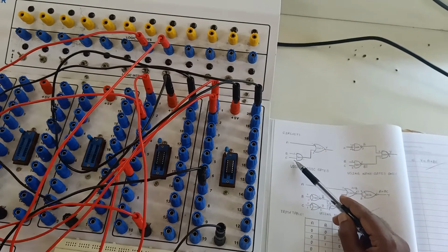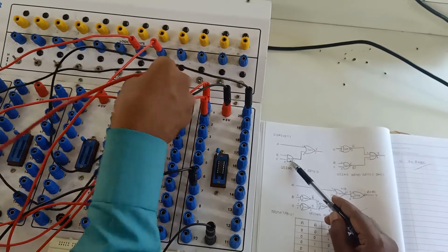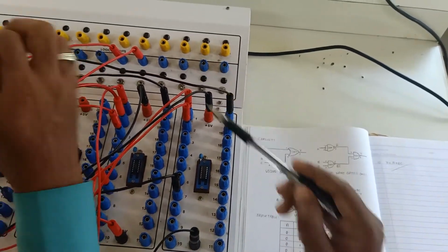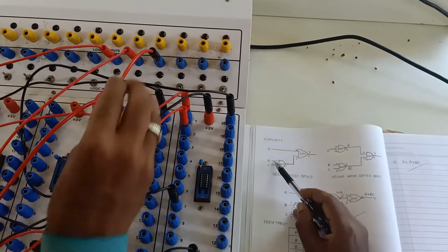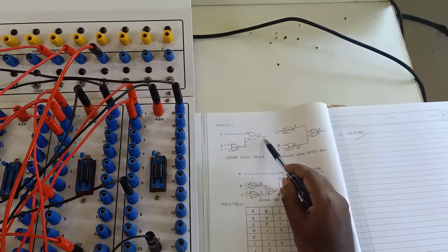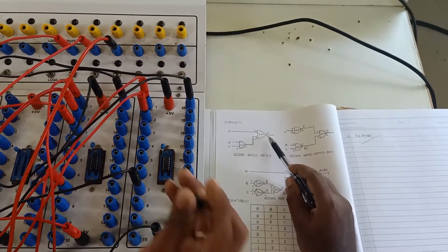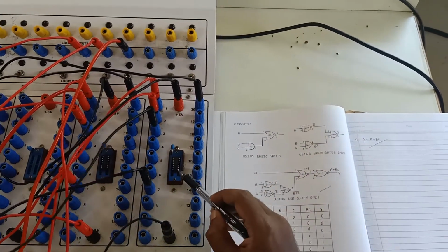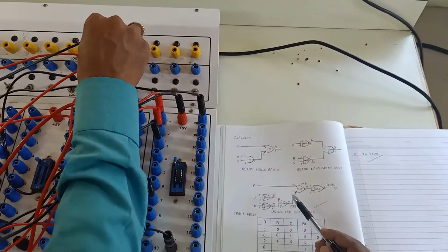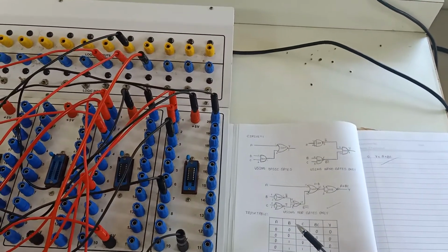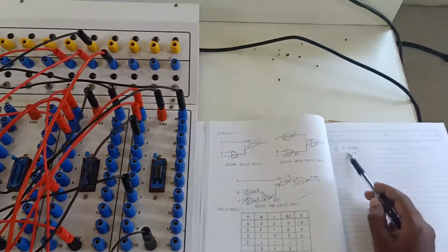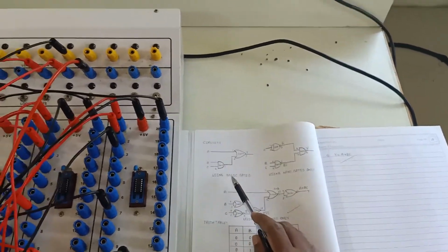Next, moving on, pin number 2 of 7408 has to be connected to where another input, right? Another actual input, again to blue line. So we completed this. We also completed this part. We were left only with this connection, right? That is pin number 3 of 7432. This is 7432 IC, right? It has to be connected to actual output, that is yellow line. To any of this yellow line you can connect. Now this completes circuit connection for this particular Boolean expression using basic gate.